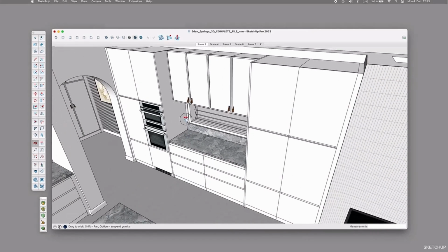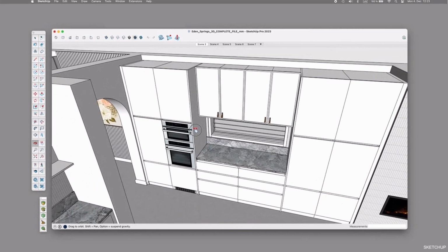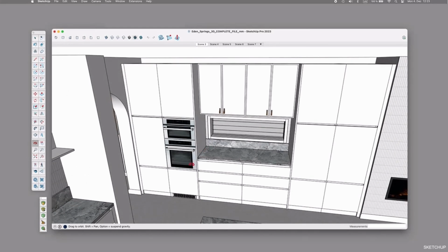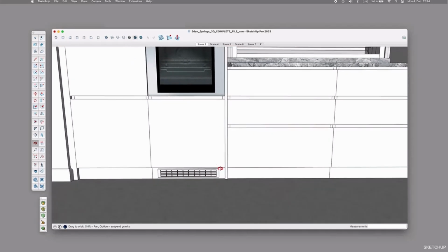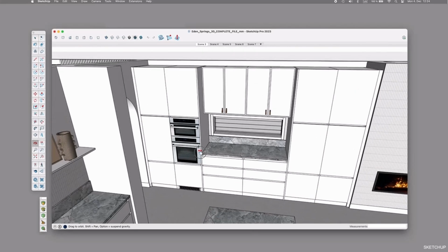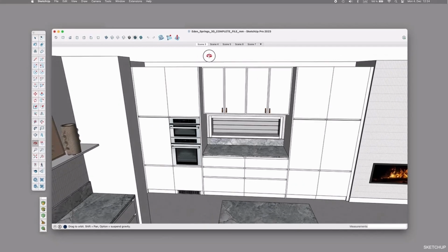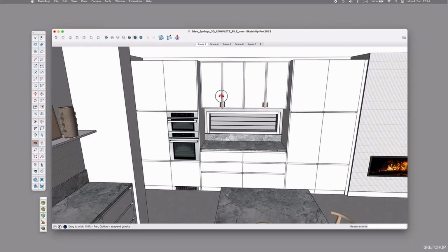Lastly, I'm not sure if I have actually mentioned that before, but ventilation is also an important factor that needs to be considered in your joinery design. Appliances can produce a lot of heat, and the air needs to be released somehow. I recommend talking to your carpenter about where he can incorporate vents for you. You can include those within the kickboard, the side of the cabinetry, or even on top within the bulkhead. Just choose a spot that aligns with your design and doesn't bother.